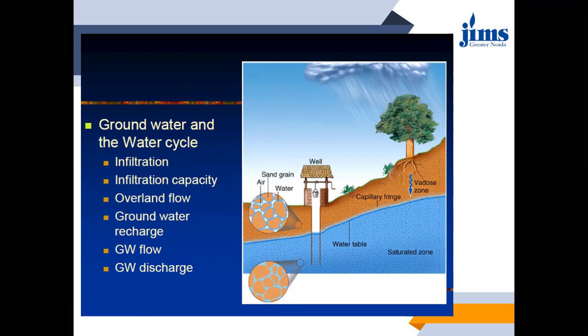How? Whatever form of precipitation comes on the ground will infiltrate into the ground surface, and only then may the water table, or the groundwater resources, be recharged. This recharging takes place when the water moves into the soil surface and earth surface, and percolates down till the water table. So whatever amount or form of precipitation comes on the ground surface, it will be moving directly where?